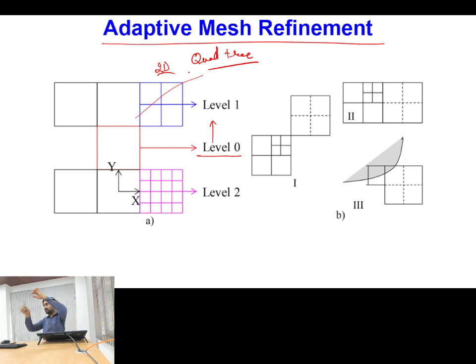Okay, so the base mesh is at the top. Upon increase of one level, that base mesh has converted into 4 cells. Upon further increase of level, this individual cell will now be converted into 4 more. So now here, if I say that in this cell I have the interface and my level is 2, then this level 1 cell is further converted into 4 more cells.